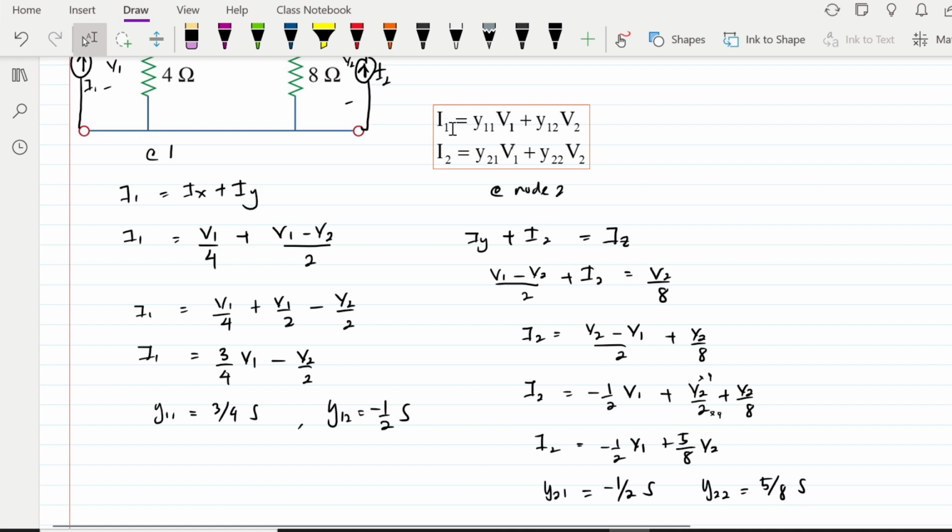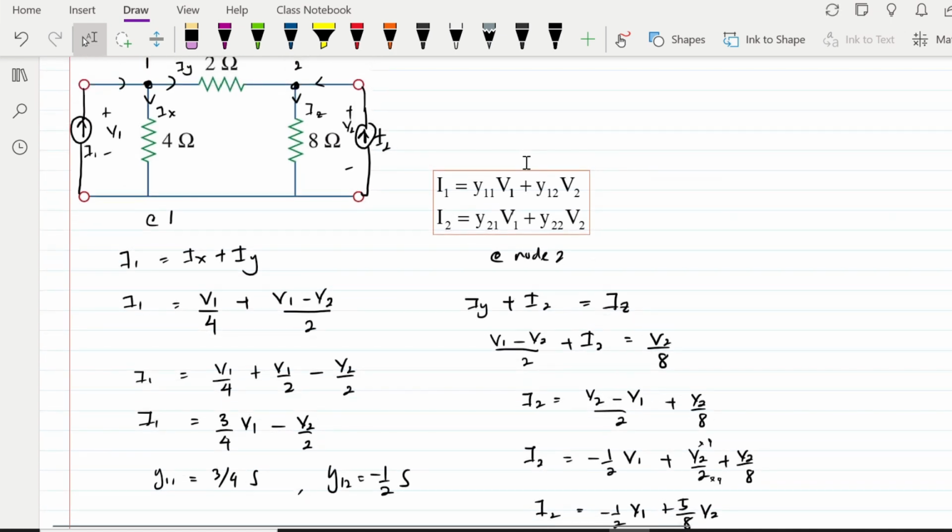You can use the conventional method where you eliminate sources. I believe I taught you before. Elimination can also produce the answer, but with maybe two more additional steps. But the circuit will look simpler, because if I short circuit here, this will be short circuited as well, so you only will have a 2 ohm resistor there. Similarly, if I short circuit here, this is also short circuited, since anything parallel to the short circuit is shorted, so you only will have a 2 ohm resistor in the circuit. So that is also easier to analyze.